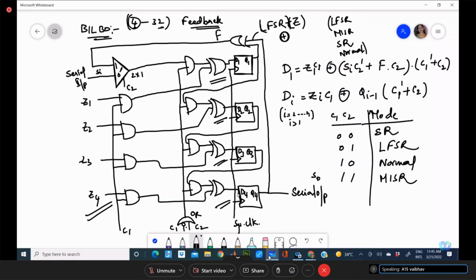Because in the last combination, we are using the total circuit except the serial in serial out thing. That means extra we are not taking anything from outside. We are generating the test pattern within the circuit, because this setup lies on the circuit board itself, and this is the response you take from the circuit you are testing. That means the IC or the circuit setup on that IC, their outputs will be tapped and analyzed with an XOR operation. That means you are doing a comparison.